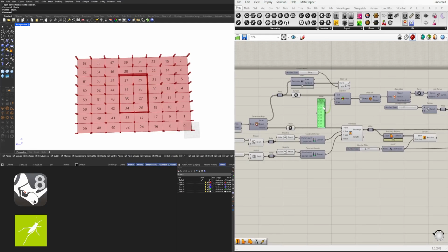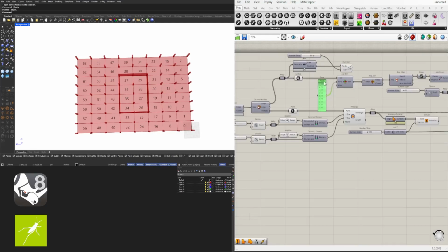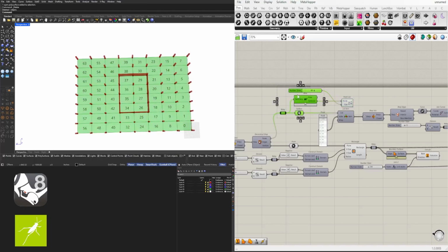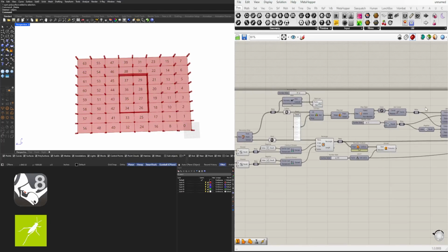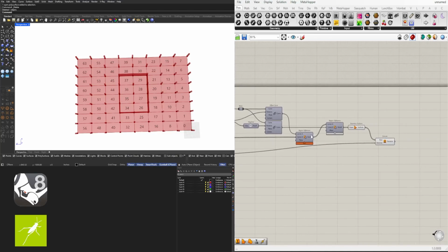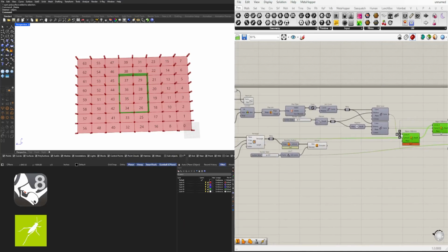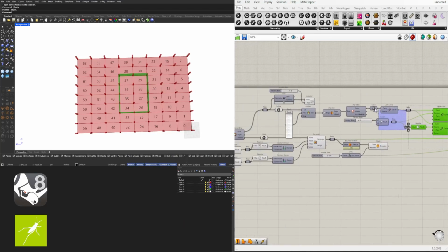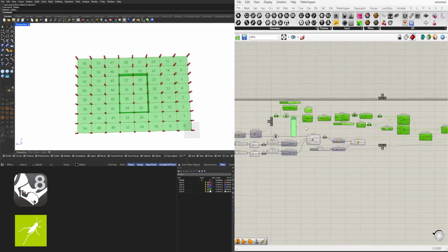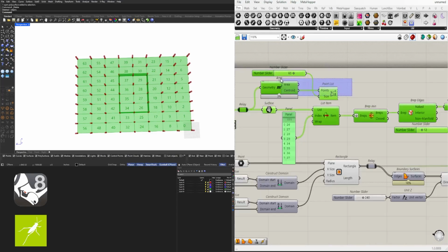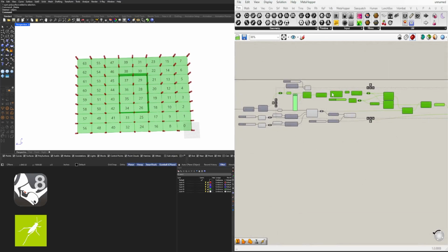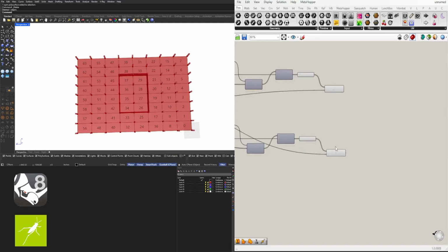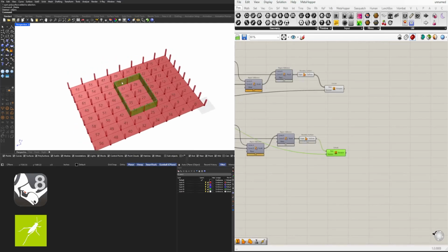When we create a set of steps inside Grasshopper, we can copy those steps and reuse them as long as we've programmed it correctly. What we'll do is we'll take this and all of this, including this panel, and we'll copy it. Well, actually, we don't need those points and the point list. We can take this, copy it down here, and we've basically recreated that set of steps.